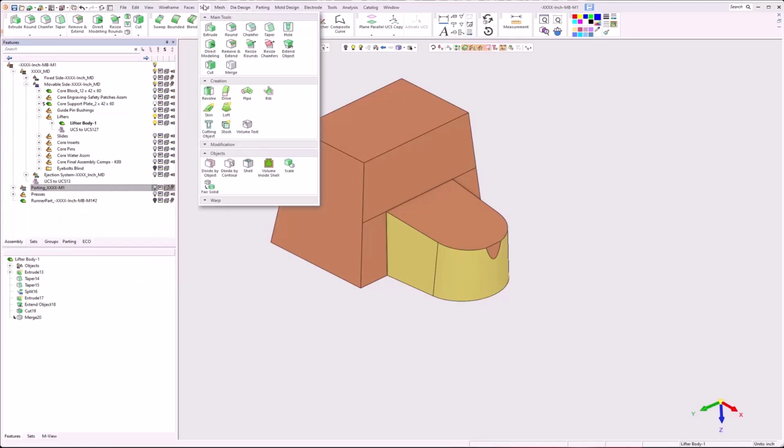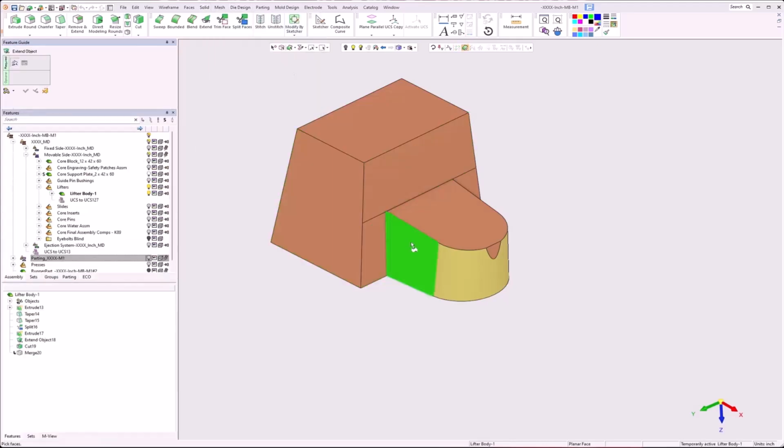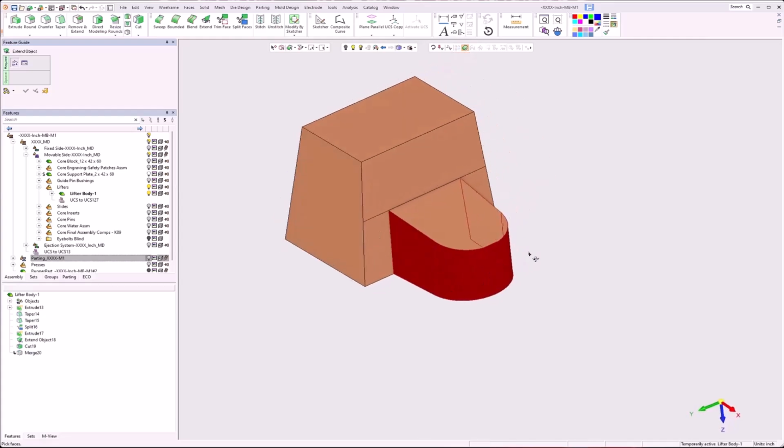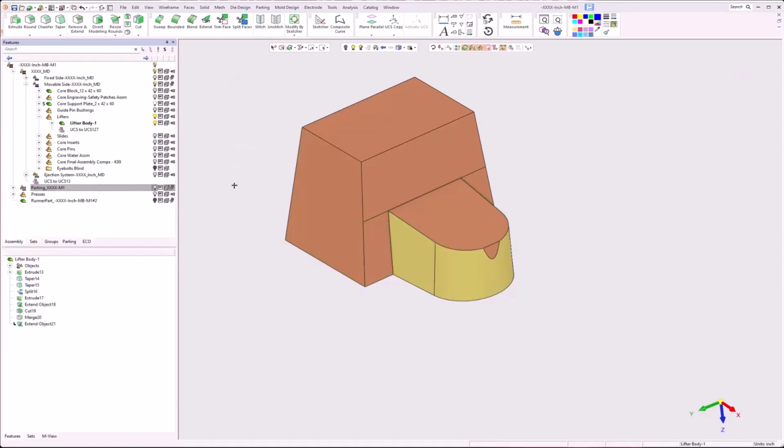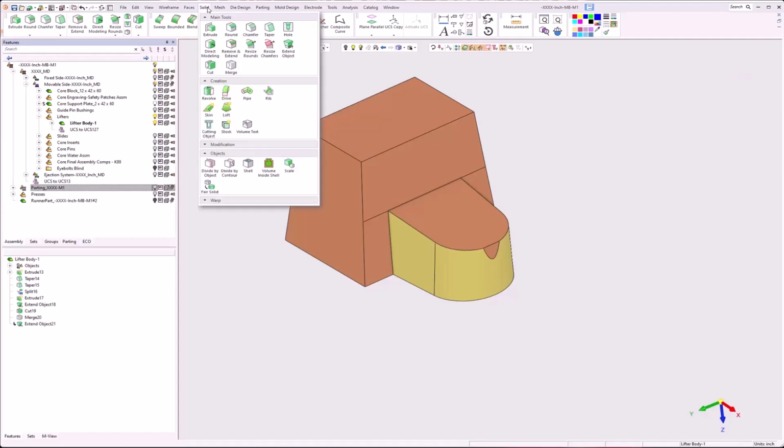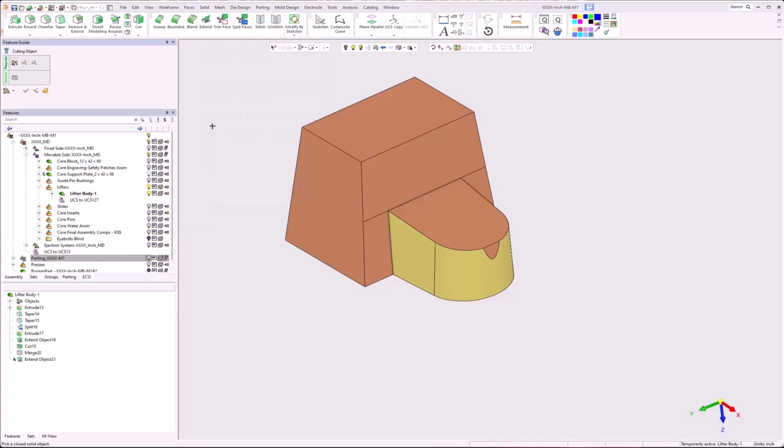And then I'm going to do one extra step here because I want to try and avoid the face for face where I can. And because I use the inside of the part, I'm going to do an offset of 10 thou outward. We're going to use solid cutting object. A lot of people don't use it or have problems with it. I think a lot of it comes down to when you apply it.